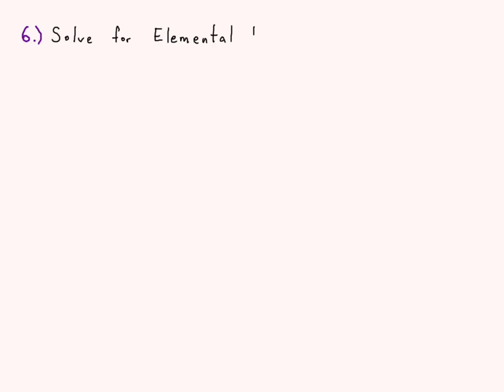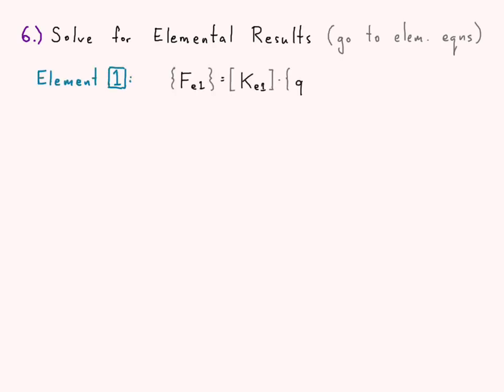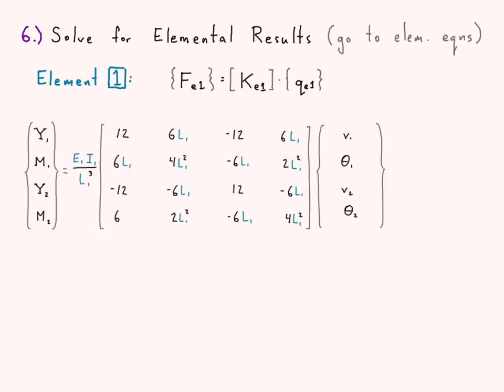All right, now we're on to the elemental results. So we use those displacement results and we go back to the elemental equations to figure out what the elemental forces and moments are. So this is our elemental stiffness matrix equation all the way back to the beginning of solving this problem. All right, and so here is our full elemental stiffness matrix equation for element 1.